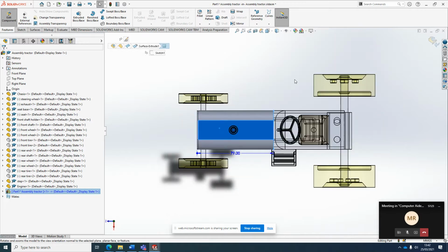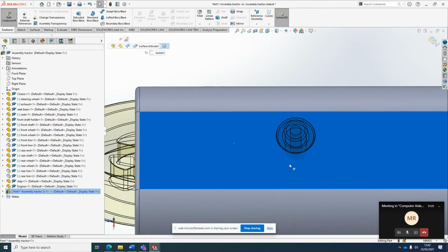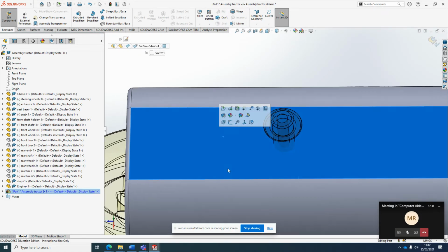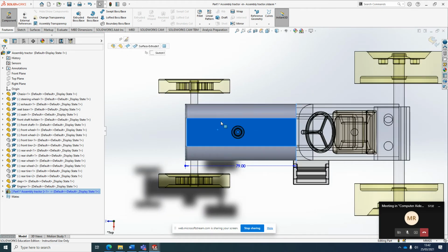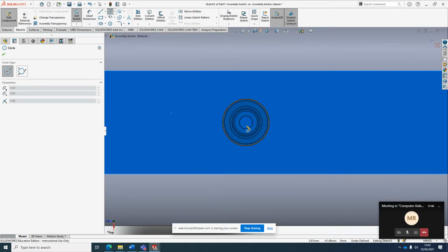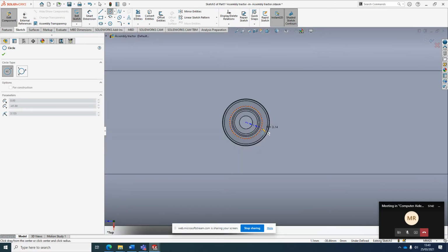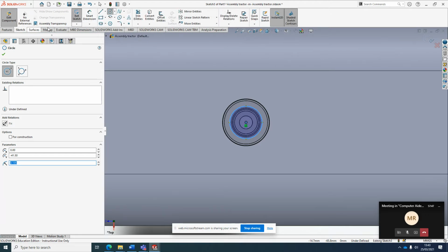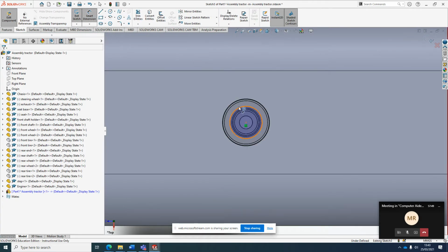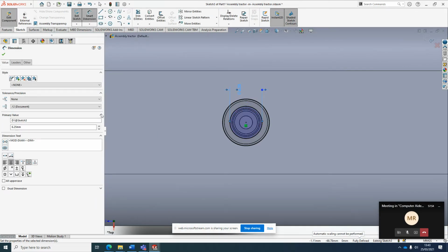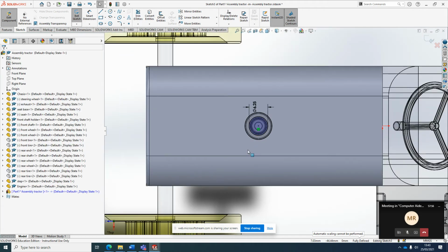Last step. At the moment there's no hole in our surface model for this exhaust. So we're going to use the features we've already used to solve this. I want to pick this surface as my sketch plane and draw a circle. Let's say it should be radius 6, maybe slightly bigger than 6. You can make that up yourself. Say 6.25. Click OK.